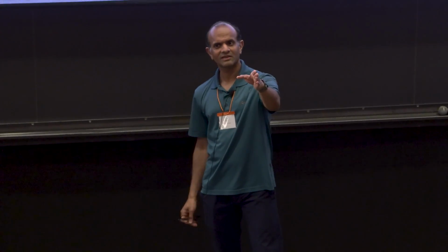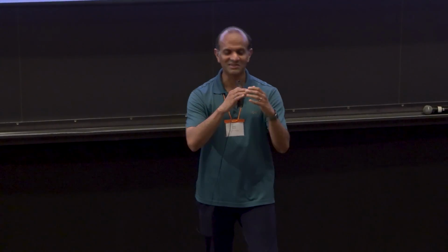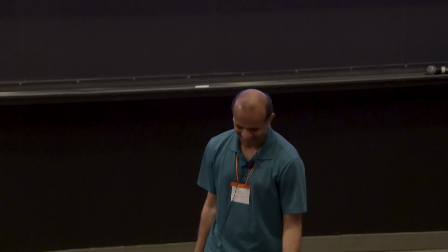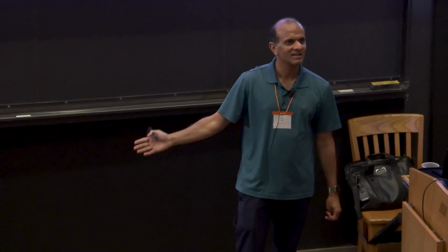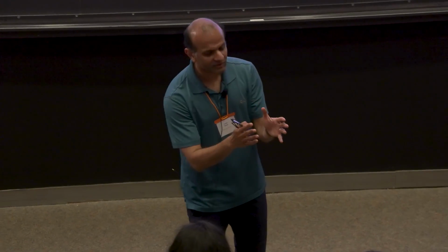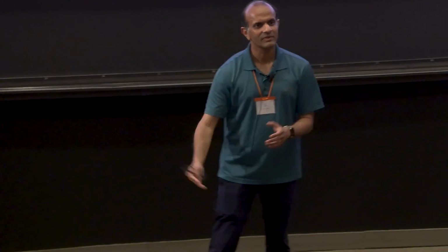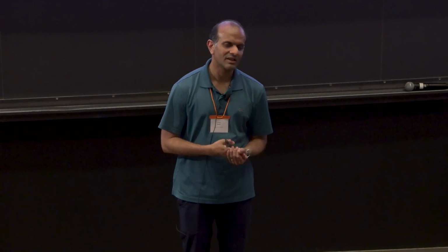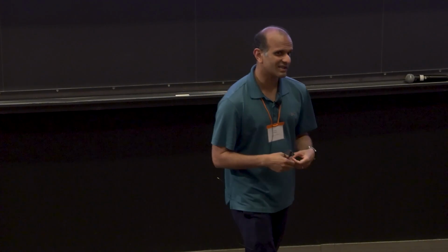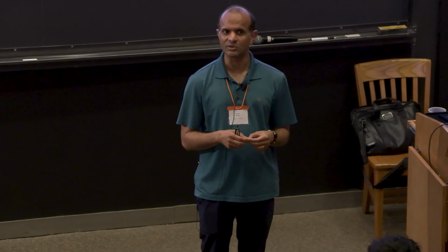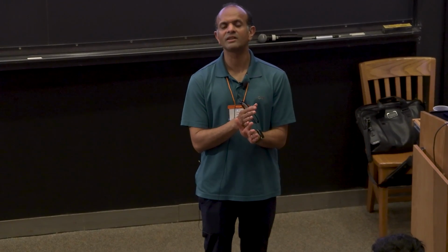So the question is, no, this is just my prelude to answering him. I'm not even close to answering him. If all of what I talked about is for premixed flames, how do you use it for diffusion flames? And the simple answer is that diffusion flames are controlled by other characteristics. There are other kinds of quantities that you need for that. So it may not be flame thickness there. It's the strain that will extinguish the flame compared to the Kolmogorov velocity, for instance, or the Kolmogorov time scale that you have. So you have to have different quantities to figure out whether flames will extinguish or stay lit.